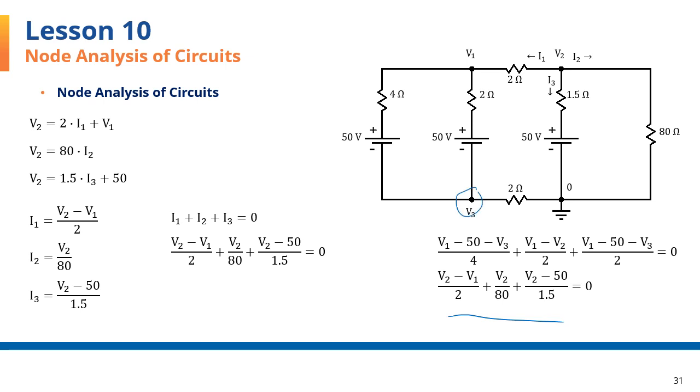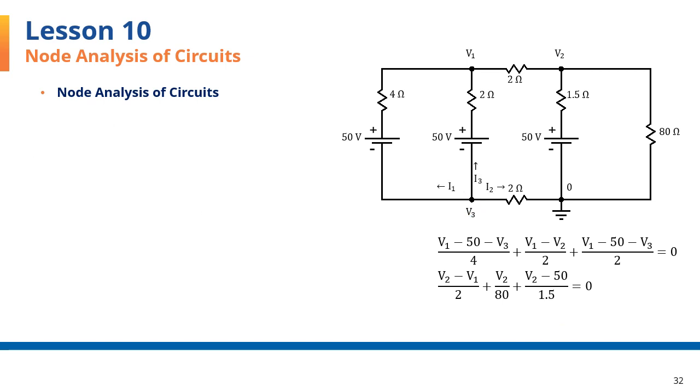Again, 3 loops for this one. First, assign the currents I1, I2, I3. The first loop goes from the reference node to V3, and from V3 in the direction of I1 all the way back to the reference point. I'll go through the equation step by step. The first voltage I come across is V3 itself, which is a voltage rise.